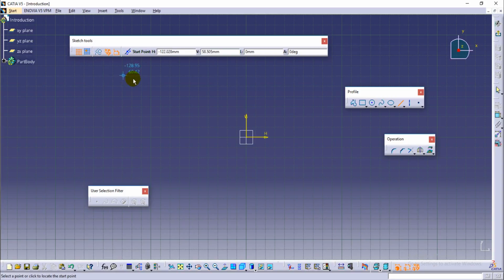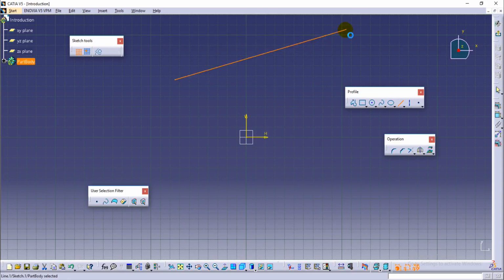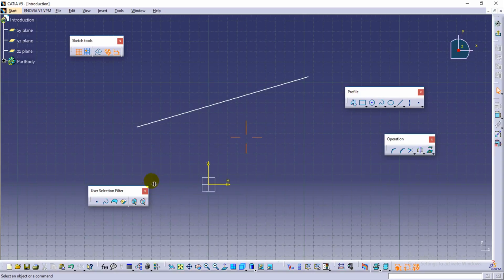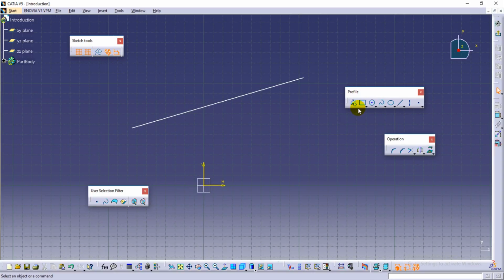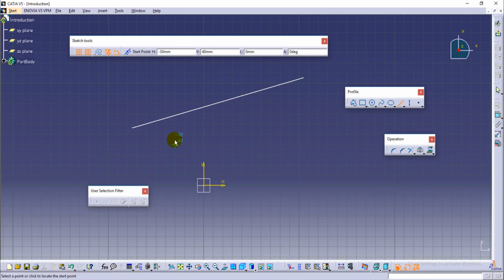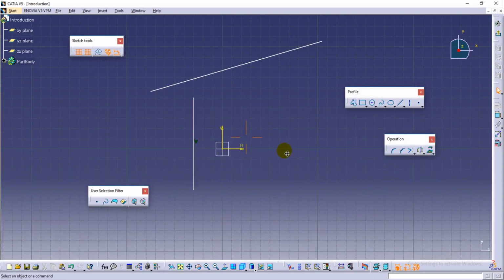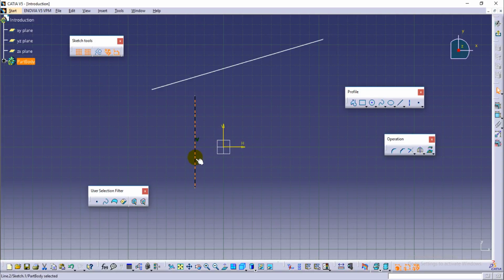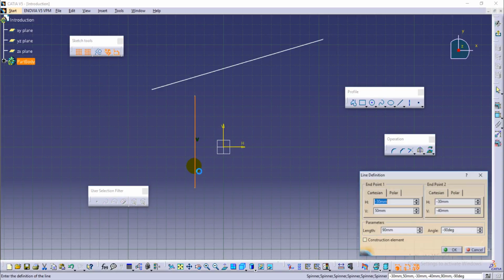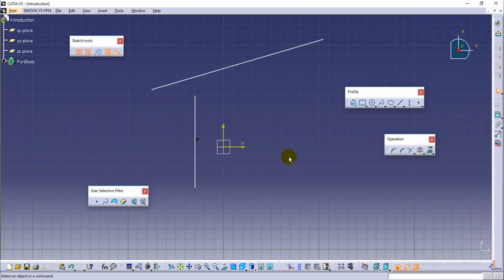If we turn this off, it allows us to draw freely from here to here like this. If we turn this on, the snapping is on, and the exact value of distances are 30, 50 in drawn figures. Okay, this is grid on and off.